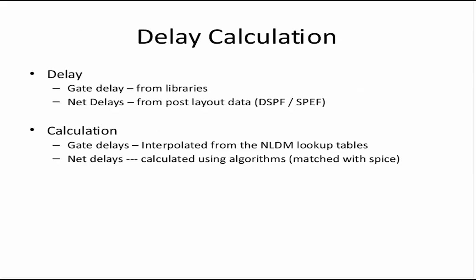Delay calculation. The gate delays are taken from the library. So this is the cell delay. Gate delay is nothing but the cell delay. It comes from the standard cell library. Net delays come from post-layout data.